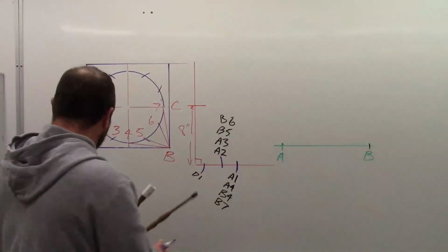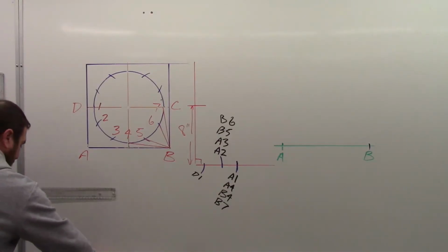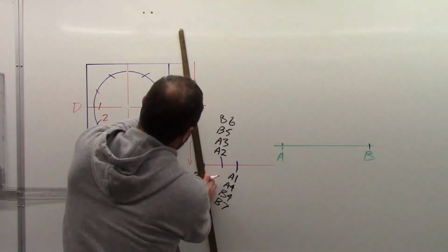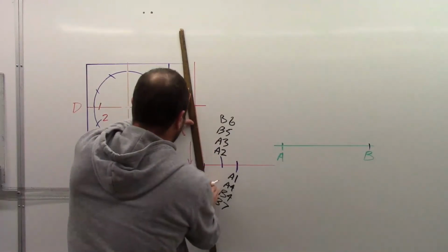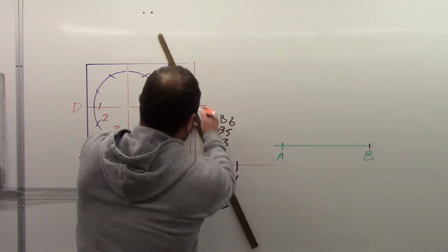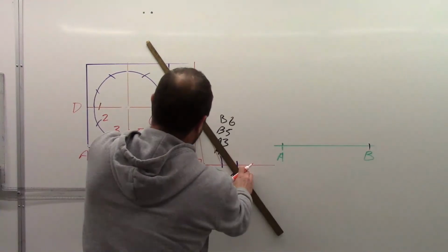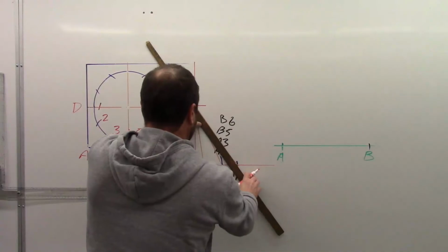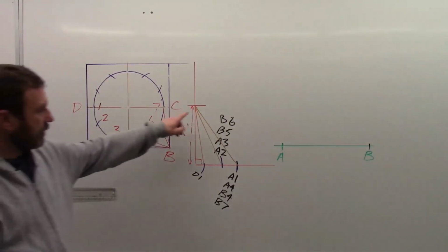So if we think of these in our true length diagram as hypotenuses, what I can do is draw those in, and again, this just adds a little bit of clarity. It's not absolutely required, but it starts to show us that if we take the vertical height against the length of the plan, it will create the hypotenuse.